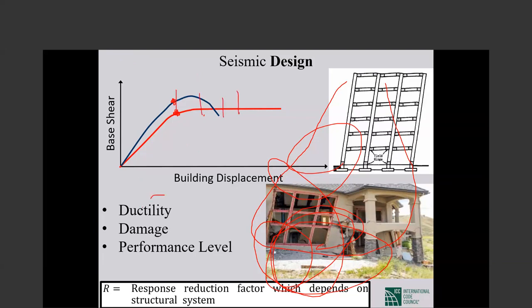Ductility is the capacity that, with our design and detailing, we can make those damaged parts behave in such a way that they get damaged, the stiffness is zero, it is a mechanism, but it can handle some plastic deformation without losing strength. This is the key: without losing strength.